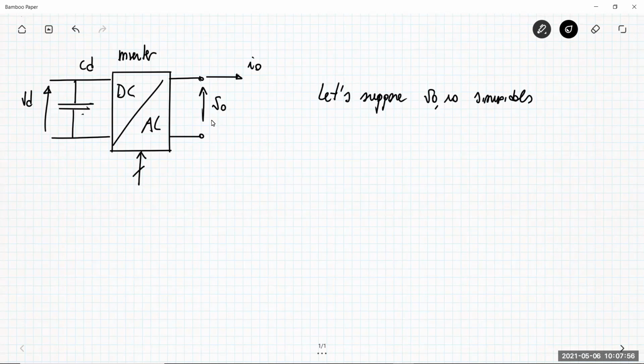Typically, for driving electromechanical actuators, the load is represented by the winding of the motors that can be modeled typically by an inductance in series with a resistance. The resistance models the ohmic losses in the windings, and the magnetic behavior of the circuits is modeled by the inductance.